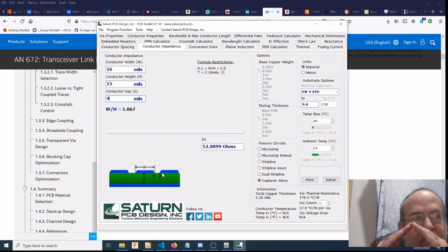As your etchant goes down, it's going to cut out. Especially if you are playing at the level of 1 mil difference, shall we say. If I have 3 mils between my traces, I'm at 49 ohms.